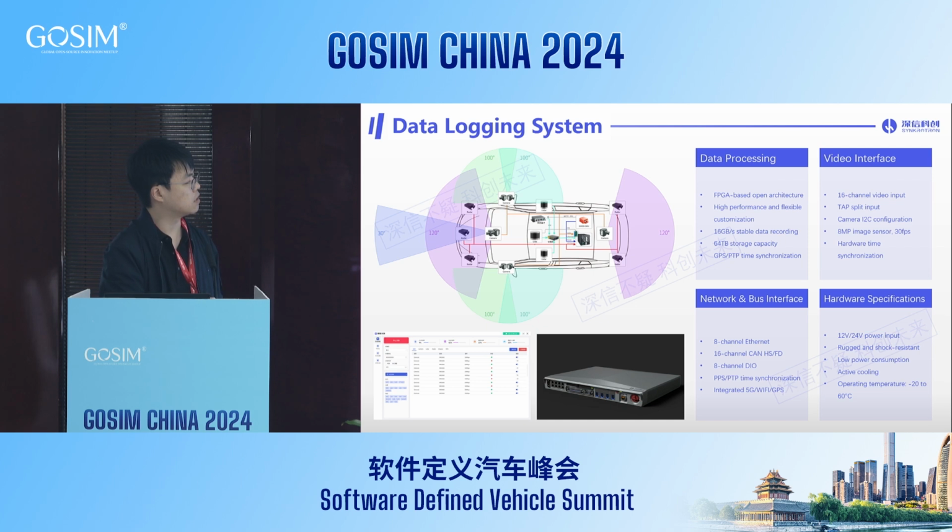In terms of data bandwidth, it needs to handle up to 16 channels of video input, up to 8 to 10 megapixels each. LiDAR point clouds will come in through Ethernet. You also need to collect a lot of in-vehicle data. The control signals always come from CAN or CAN-FD signals. So these control signals, or the status of the car, need to come into the data collection PC as well.